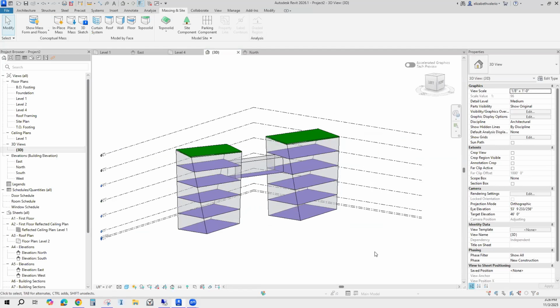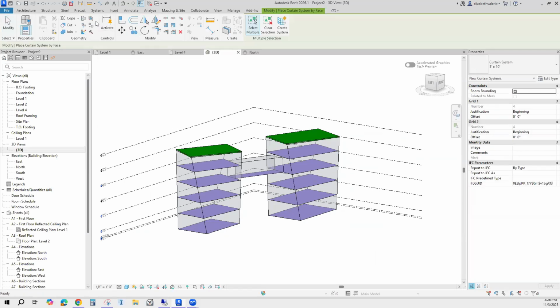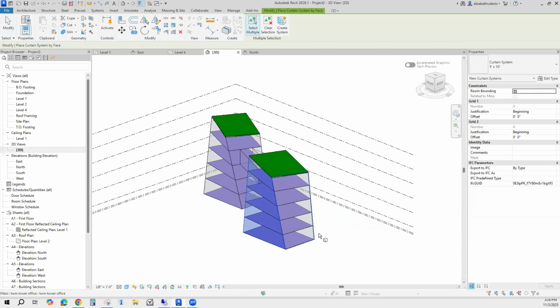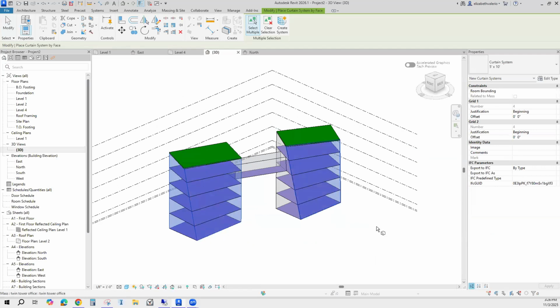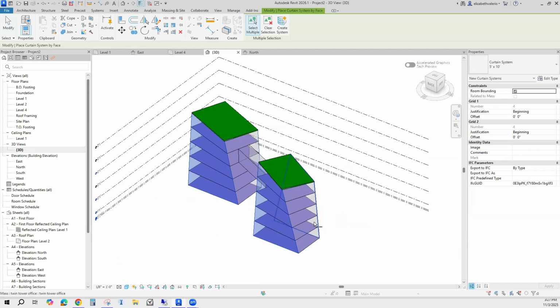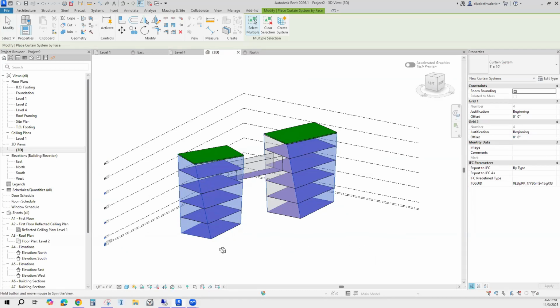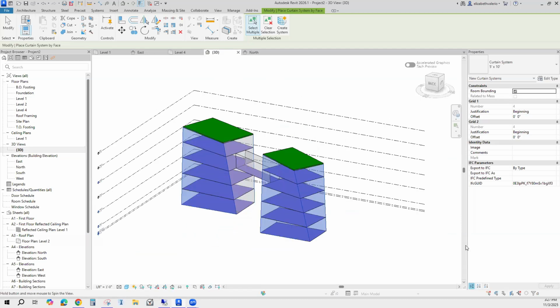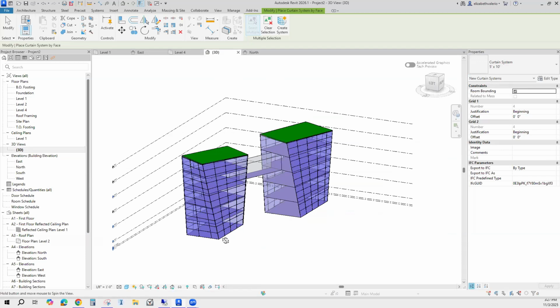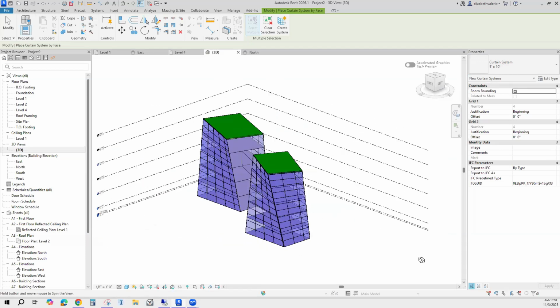Then I need some walls. I'm going to do curtain wall systems. So I'll click curtain system, and I can select the faces that I would like to create curtain walls from. All right, so I'm grabbing 3 walls on each building. I can choose a curtain wall system, create a system. I'm going to keep the default, enter. So we get some windows on those exterior walls.